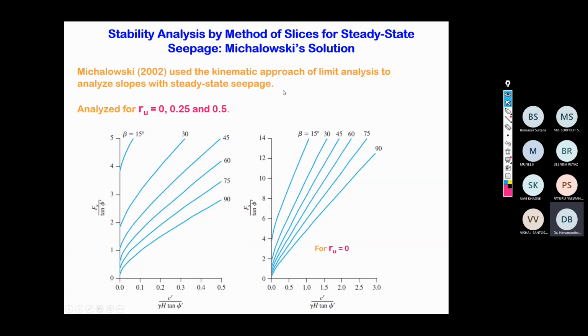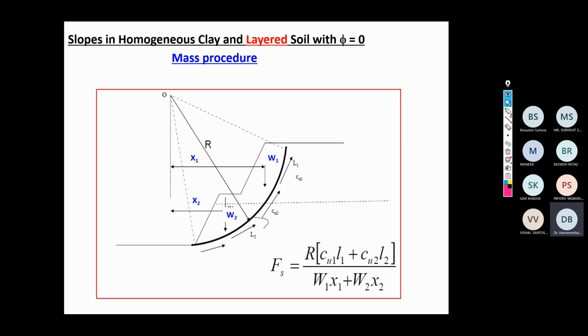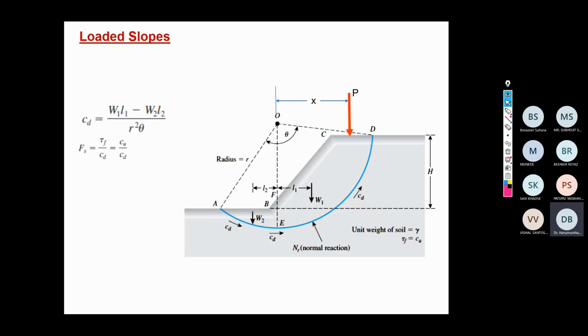Similarly, Michalowski also proposed another set of charts for computing the factor of safety when the slope is subjected to steady state seepage condition. These are the Michalowski charts. So this will be it.